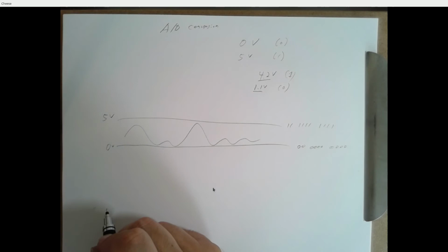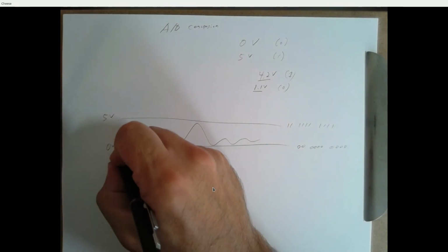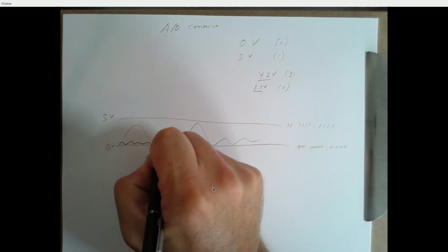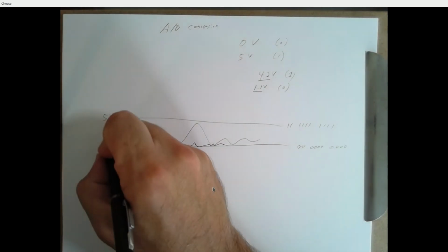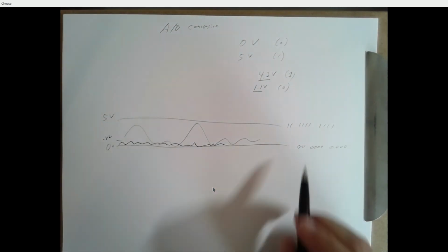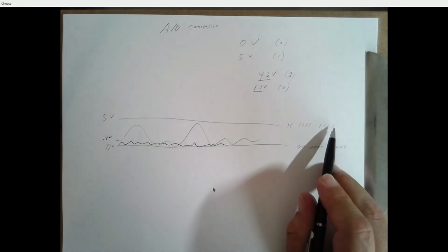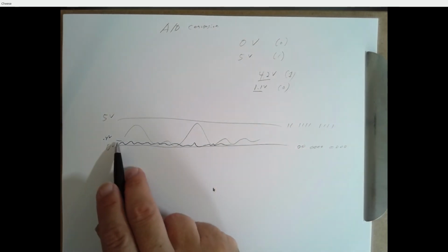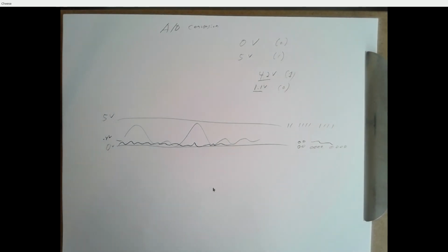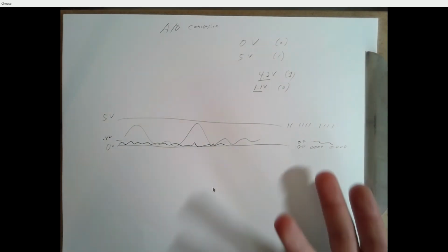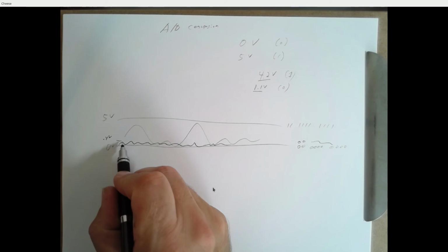Okay, but now suppose we have another signal coming in, and this signal only varies from say 0 volts to 0.4 volts. Well, if all zeros is 0 and all ones is 5, then the value for 0.4 volts is going to be pretty small, right? We're not going to be using this full 10-bit range to represent all the values that